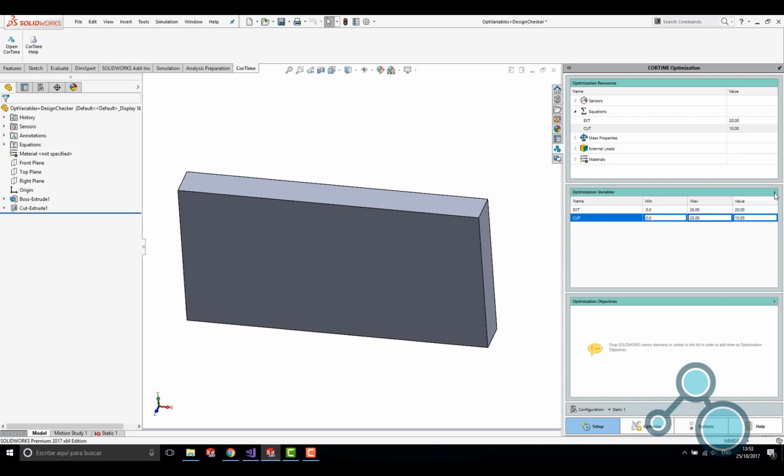If we click on the right arrow, we display a new menu under the window. The first button, Show Step Size, will give us more information about the variable. We'll get step size, number of steps that it's going to take, and the step anchor that represents the starting point. If we select one of the variables and turn it into continuous, we see that the values disappear. That is because in a continuous range, it can take any value inside the range. If we select another one and we turn it into integer range, we see that the step size turns into 1.